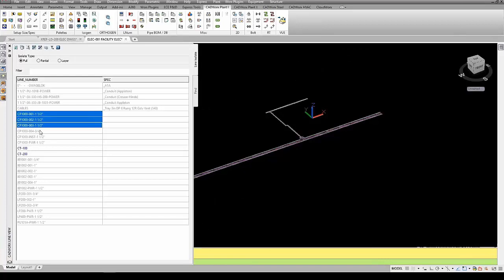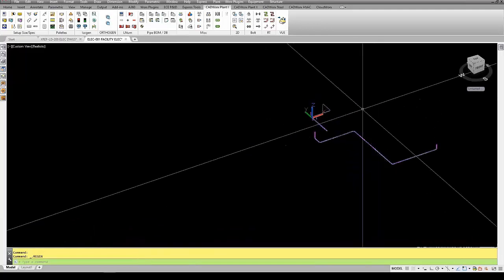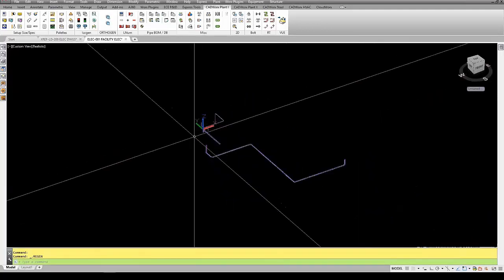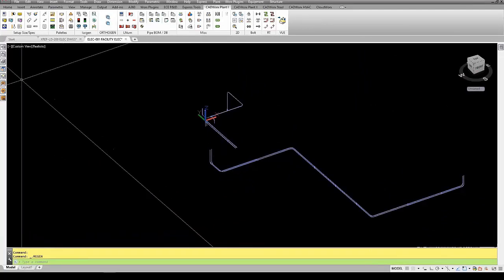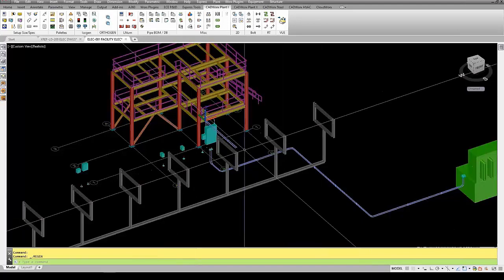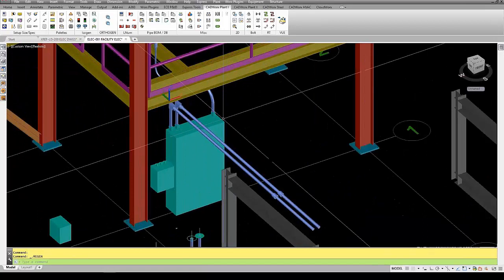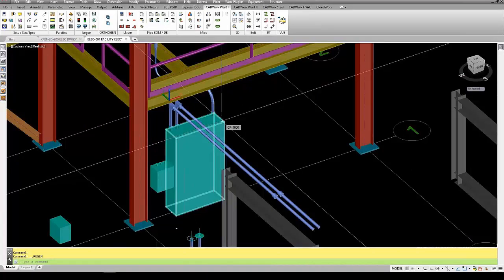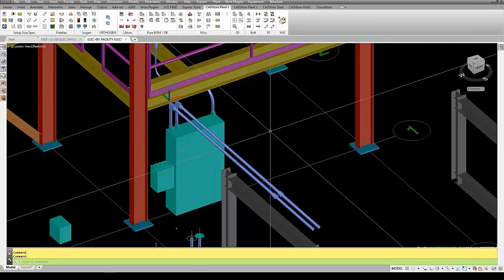And then if we want to look at the control panel 1000, we've got conduit coming in and conduit coming out of control panel 1000. Just by the naming convention of the conduit, we can see this. Let me do a partial here. Partial with the isolation will bring the CADWorx objects such as the structure and the enclosures back into view, so I get a nice visualization there. And there's our line number.